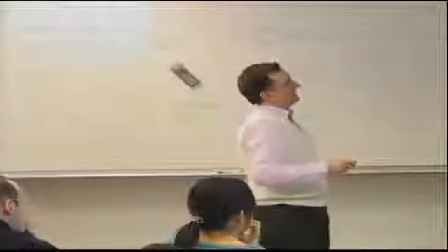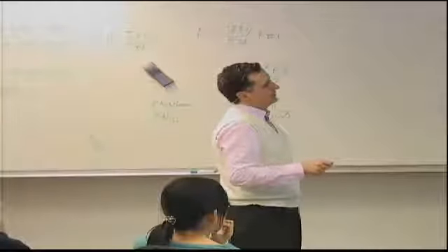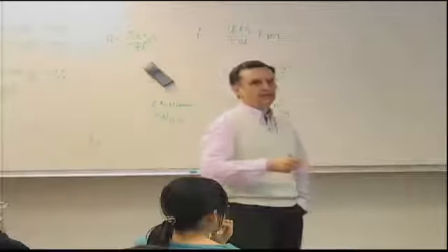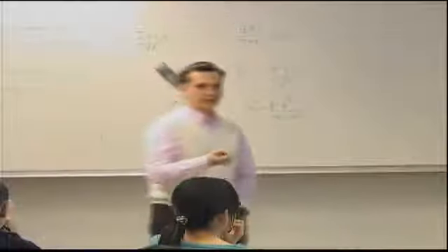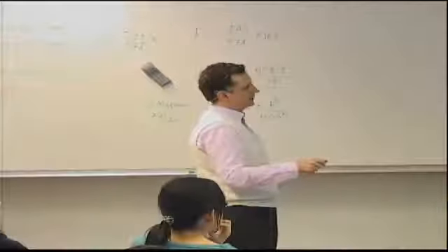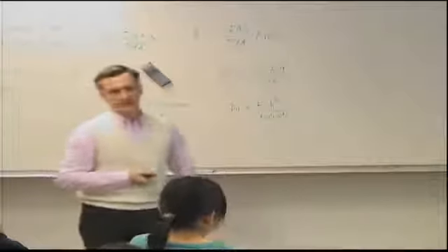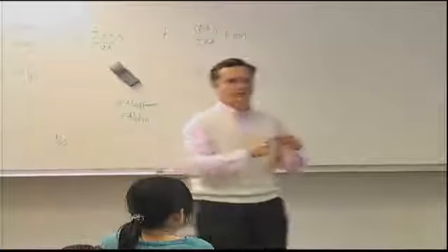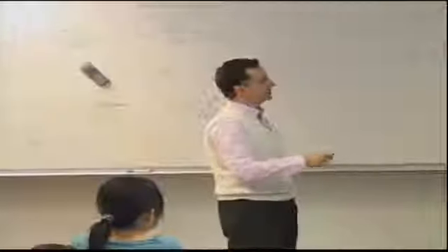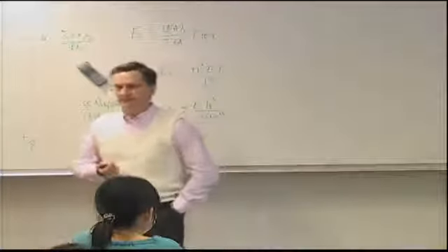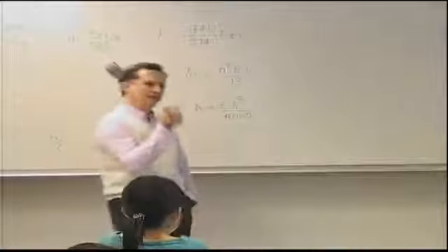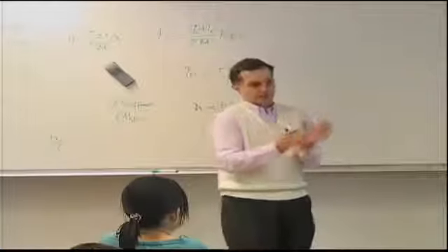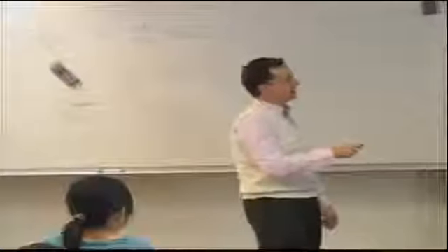Now, that means that the fact that I have load on either side of a fastener means that this load, P minus P1, let's say approaching the second fastener, will see the stress concentration effect of the second fastener. And the load P approaching the first fastener sees the stress concentration effect of the first fastener. The closer the fasteners are, the more they interact with each other. So if in an infinite plate there would be a stress concentration factor caused by one fastener, which is not 3 because the fastener has a bolt in there, it's less than 3, but it's significant. If I have a finite plate with fasteners next to each other, this stress concentration factor is increased by the presence of the other fastener next to it.